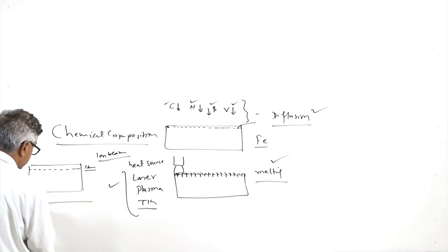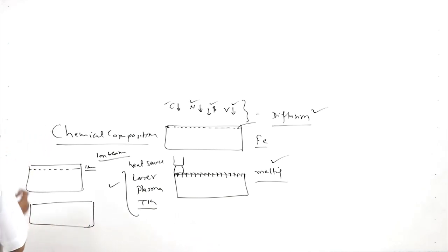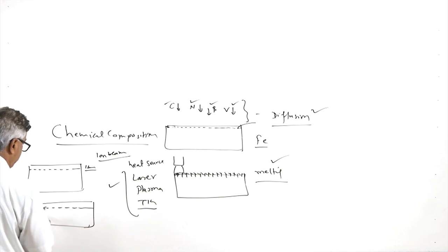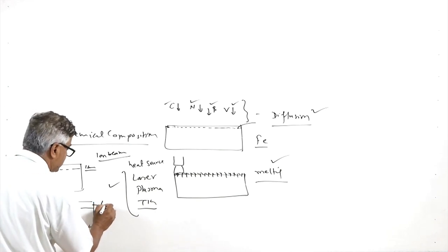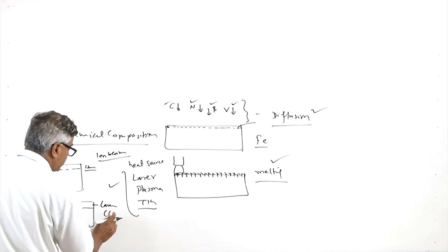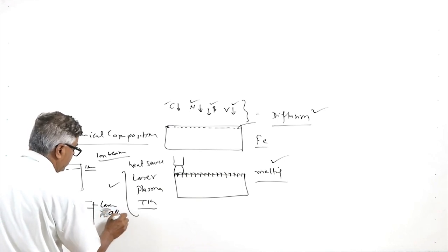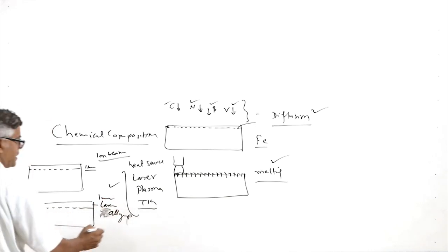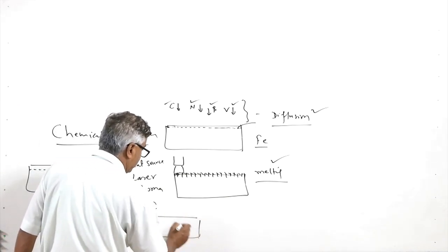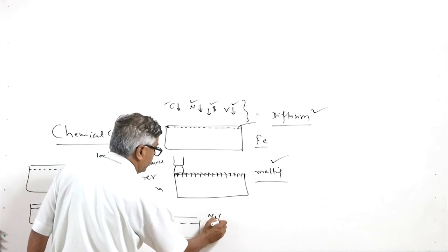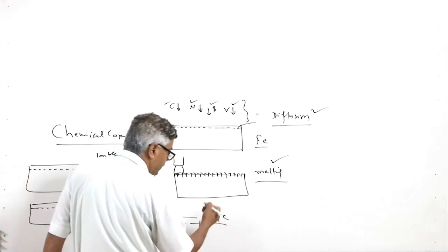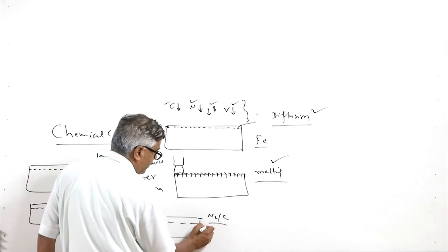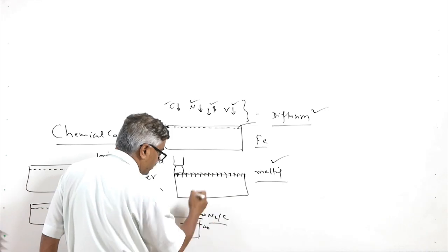While in other cases, say in the case of laser cladding, laser alloying or TIG alloying, the modified depth may be even 1 mm or so. In other cases, where nitrogen and carbon are introduced at the surface in carburizing and nitriding methods, this depth may be from 100 microns to 1000 micrometers or even more.